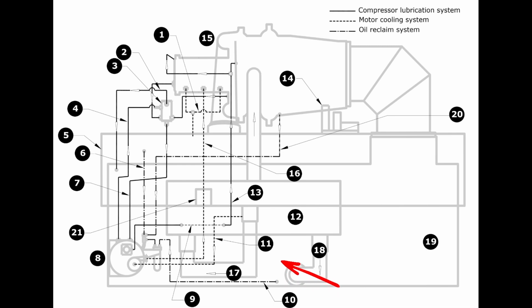A lot of times they'll be more up here towards the midpoint, which is about just a little bit above this flange. For these CVHs, they actually run a pretty low liquid level compared to the size of the evaporator. So you may have your liquid level right up here. Right about there, it's pretty common to see that. Regardless,